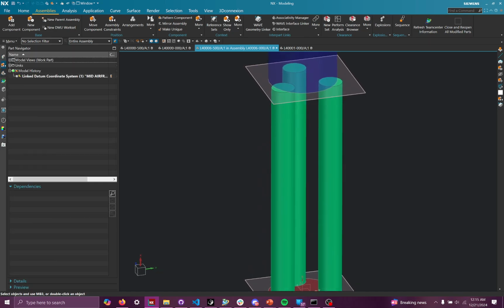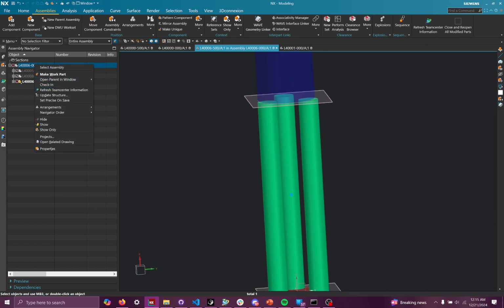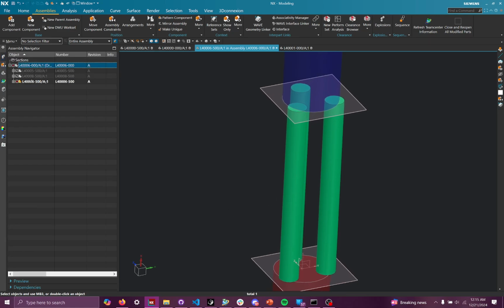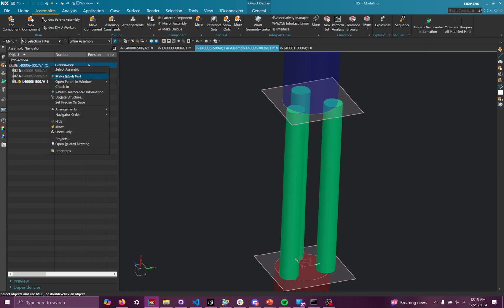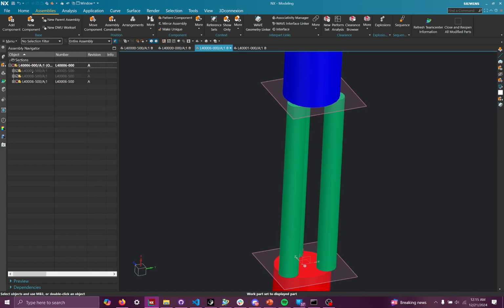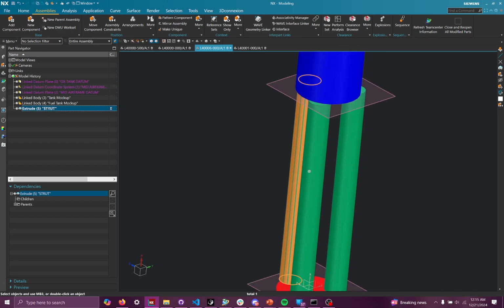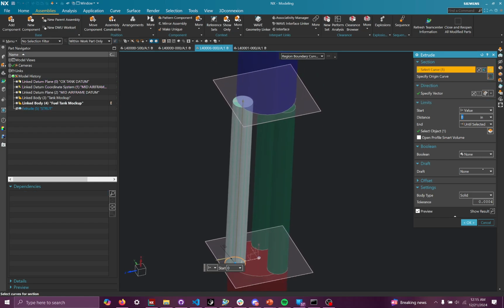Firstly, though, it's really annoying me that, oh, I'm still within the assembly file. Okay, I just lost myself a little bit. I was looking for the extrude that defined this strut, but since I'm within the assembly file, since this is my active work part, I can't see that. So I actually have to move a layer up by making the layout file the work part. So clicking on that, I can go into the part navigator, see the strut, and I want to make this strut thinner. It's really bothering me that it's like 3 inches thick.